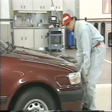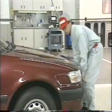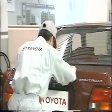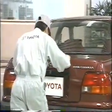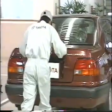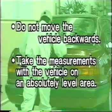Bounce the vehicle up and down to stabilize the suspension. Move the vehicle forward about 5 meters with the front wheels in the straight-ahead position on level ground. Do not move the vehicle backwards until the measurement is completed. Take the measurements only with the vehicle on an absolutely level area.